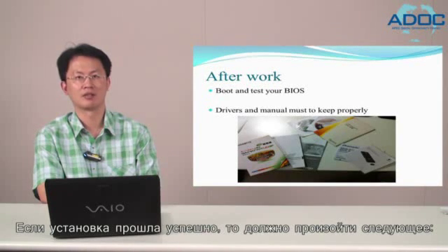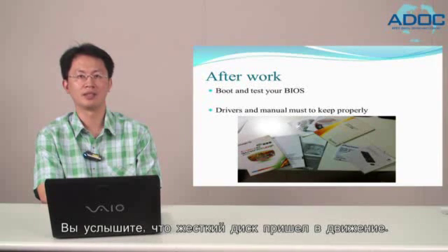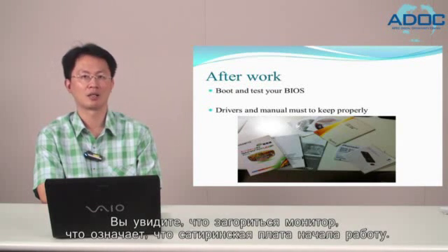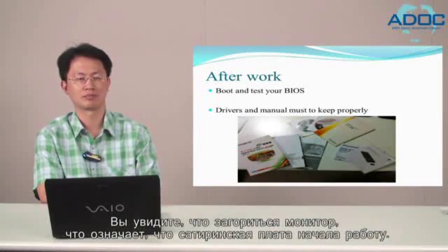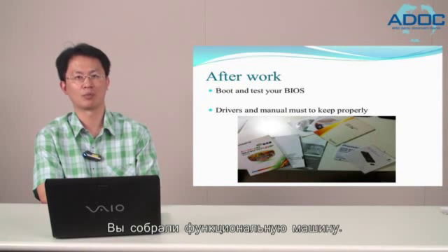In the ideal case, four things will happen. You will see and hear the fans spin up. You will hear the hard disk spin up. And lights will light on the case. You will see something happening on the monitor to indicate that the motherboard is alive. If you see and hear all of that happening, you are successful. You have created a working machine.